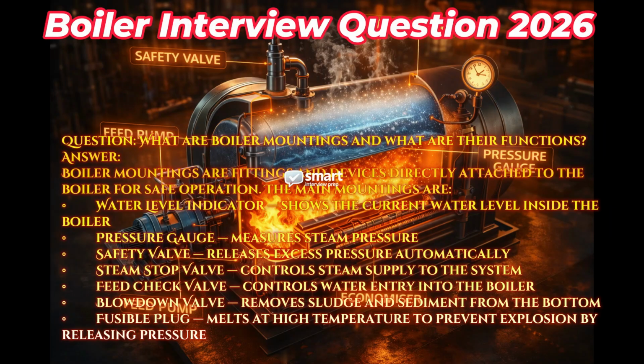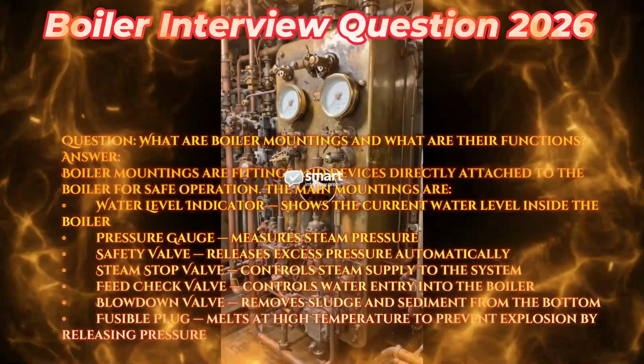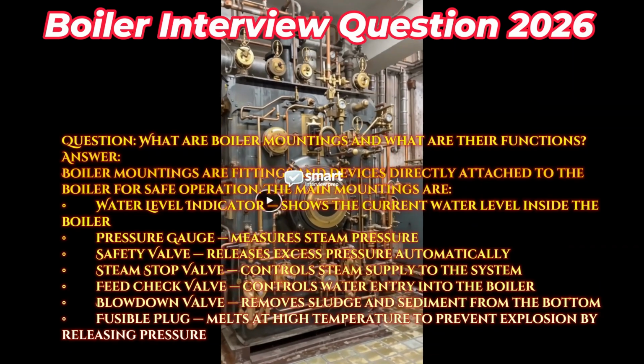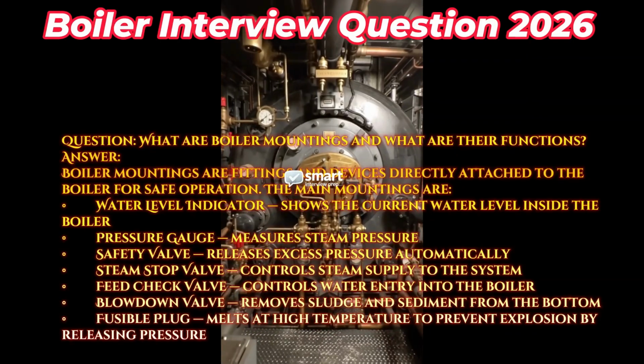Question: What are boiler mountings and what are their functions? Answer: Boiler mountings are fittings and devices directly attached to the boiler for safe operation. The main mountings are: a water level indicator, shows the current water level inside the boiler. Pressure gauge measures steam pressure. Safety valve releases excess pressure automatically.